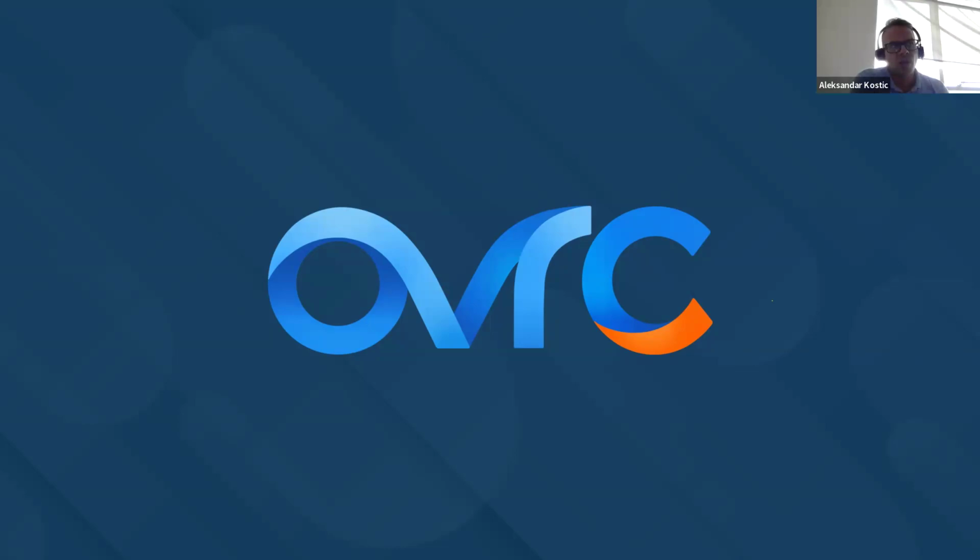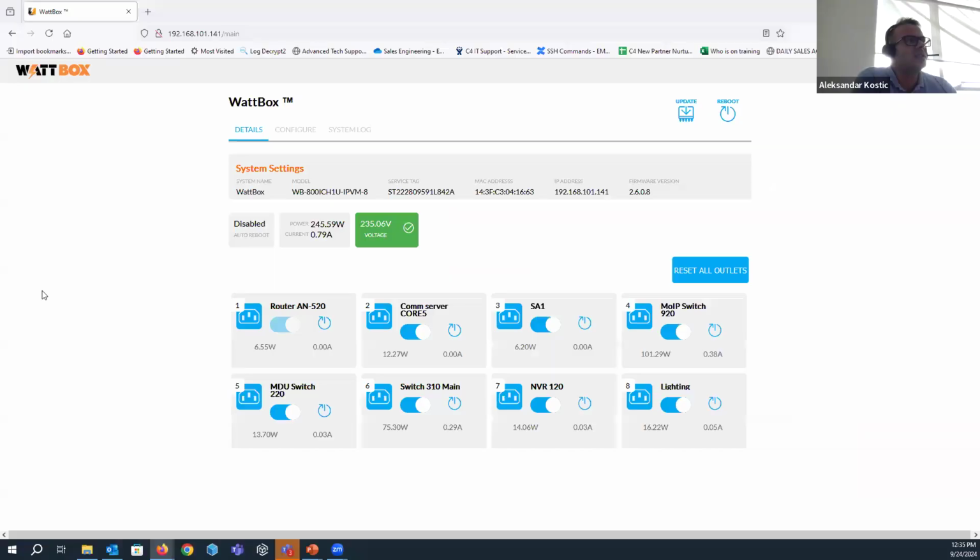I explained at the beginning that full utilization of the WattBox and all the features are available through the OVRC. I can show you, for example, how the local web interface of the WattBox looks. So this is my local web interface, and as you can see here, I have just the basic control of my power outlets. I can restart, enable, or disable them, or reset all at once.